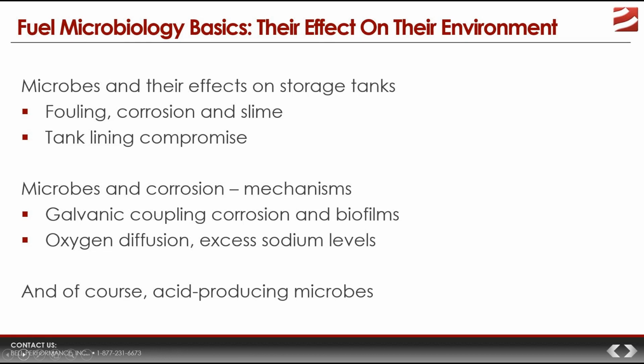Now, when we talk about storage tank damage, we are used to it being primarily defined as corrosion. But we know that corrosion has to do with reactions with metal, and there's plenty of damage going on with non-metallic parts of the tank. So let's talk about non-corrosive damage. Non-corrosive damage and issues are characterized by things like fouling.